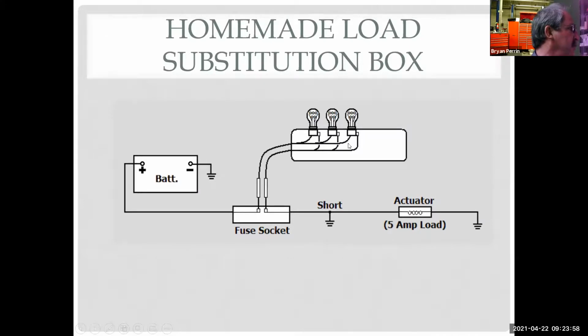So we took the fuse out, put the substitution box in its place. The light bulbs are all bright. As soon as I'm no longer touching ground here, the light bulbs are going to go out or get extremely dim. I've just found my problem. So this is great because I can wiggle wires. Are my light bulbs now getting dimmer? Are they flickering? Tells me that, oh, I'm on the wire that has the problem. So this is, again, a different way of diagnosing the problem.